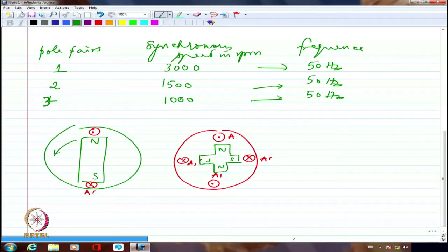So, between this north pole and south pole, although it is 90-degree displacement, I am actually having 180-degree traversal as far as the electrical current is concerned. So essentially the traversal of the electrical degrees is being divided by 2 when actually I come to the mechanical degrees. This is what I am trying to emphasize, right?